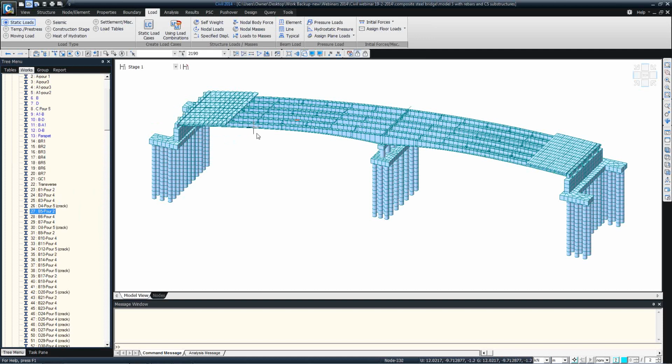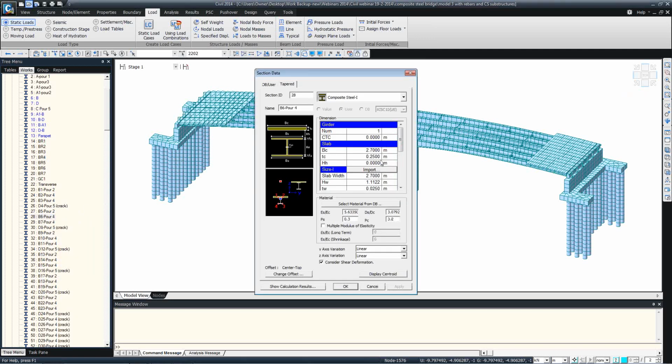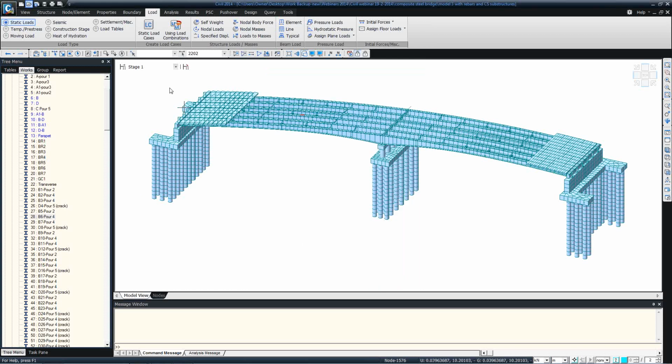The other important thing in curved bridges is that you should also create intervals whenever there is splicing to get the splice forces. So that's why you can see the nomenclature that I've used here is based on the splicing information. So if this is girder B, then I have splices at 7 locations, and I've named them separately. And each pouring sequence has been named with different composite sections. They can be the same section, but just name them differently.